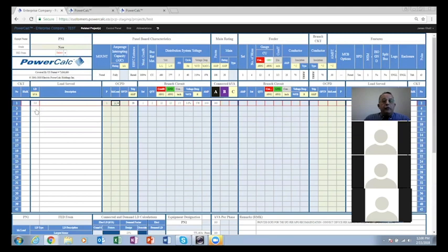So this particular circuit, the 3 kVA, single pole, is a power load. It calculated the trip for you, the trip amps on the circuit breaker, and it requires on the branch circuit 1 set of 2 number 12 conductors and a number 12 ground in a 1/2 inch conduit, and calculated the voltage drop and the maximum distance for that particular voltage drop.